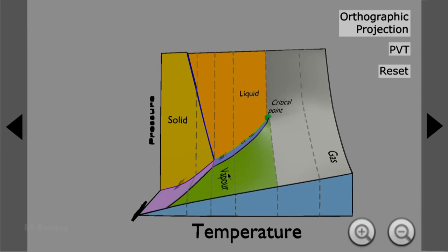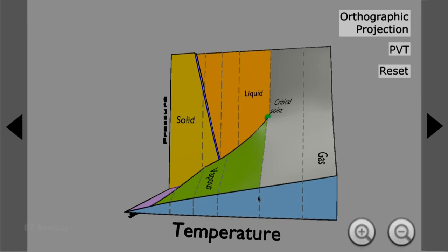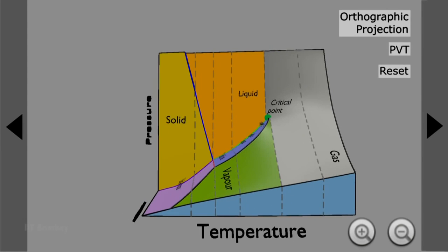What you also see in this particular direction are the isotherms. You can see the temperature lines over here, and you can see a temperature line that goes through a critical point, and this temperature is called the critical temperature. Corresponding to this critical point, the pressure is called the critical pressure. And what you can also see is that beyond this critical point, beyond this critical pressure, there is no phase transition line from liquid to gaseous region.